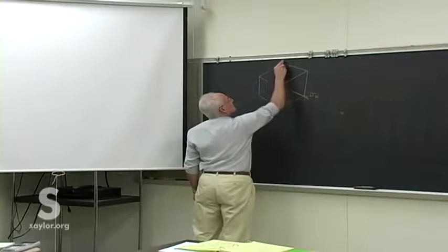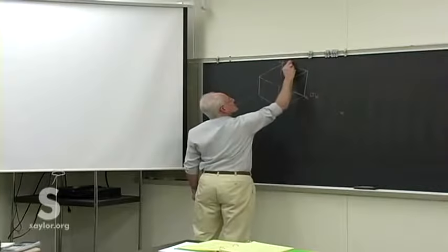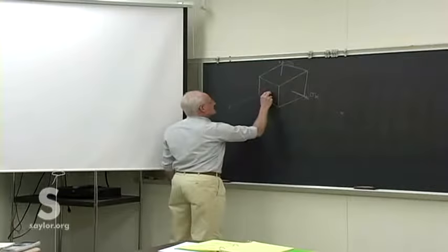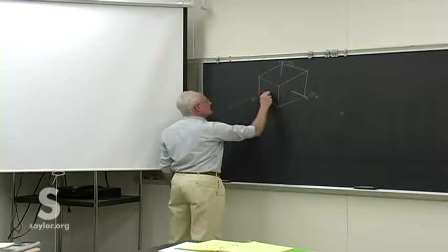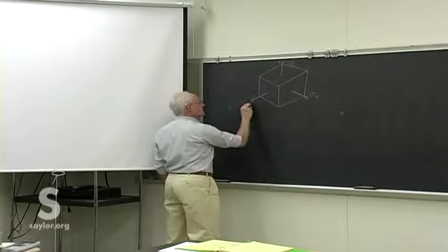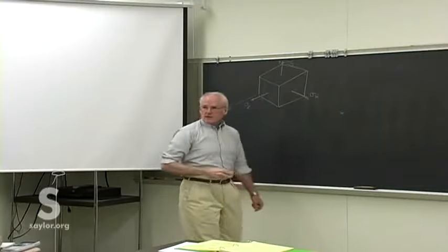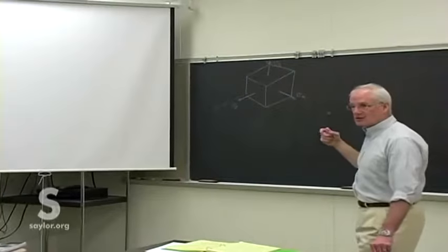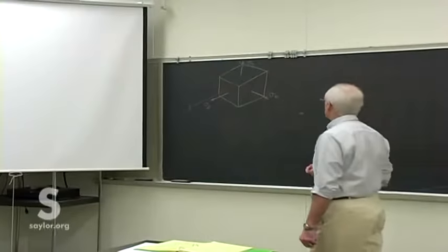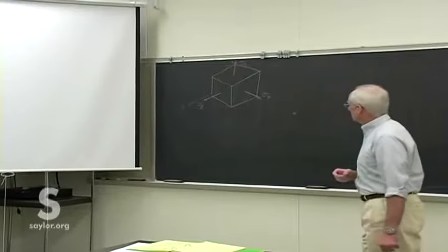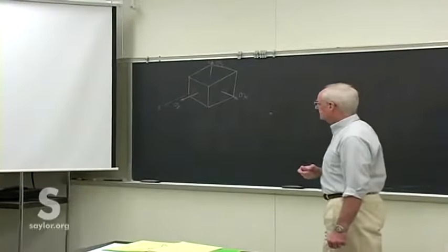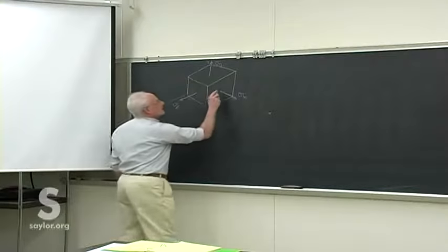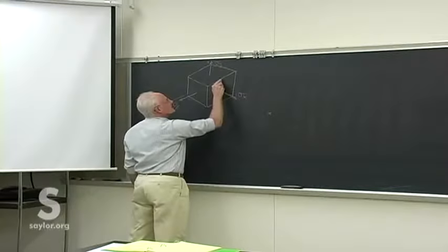There might be some normal stress in the y direction and in the z direction. Depends on what the problems are, what the loading is. That's what we saw in the problem that was just on the board. That these stresses can even change for different places in the same piece, just because of the variation of bending across the cross sections. There might also be the possibility of some shear stress.